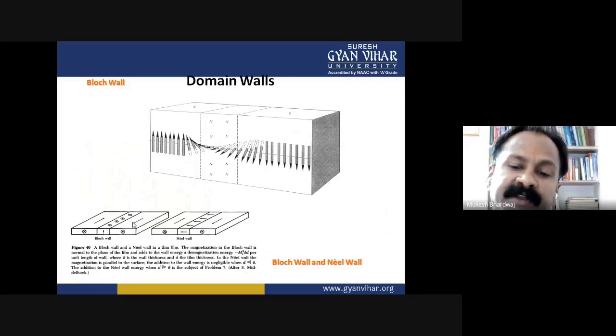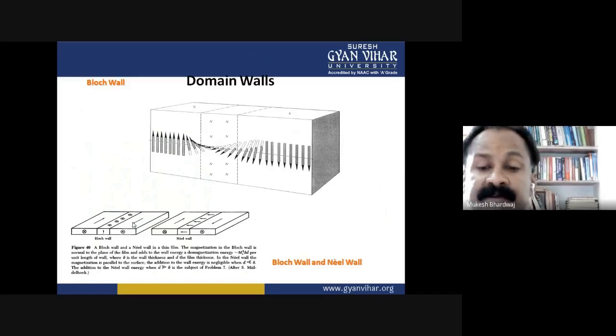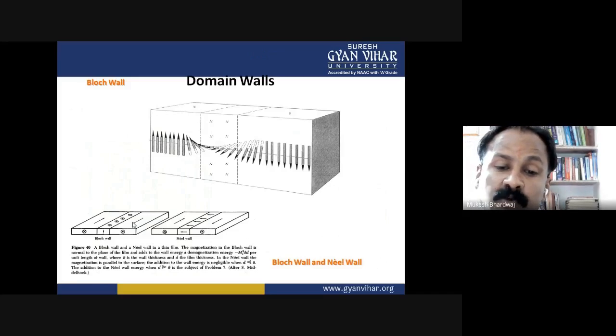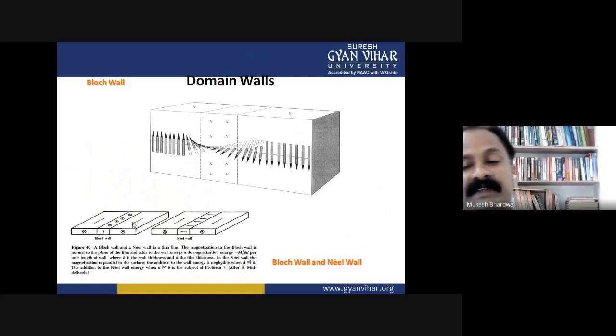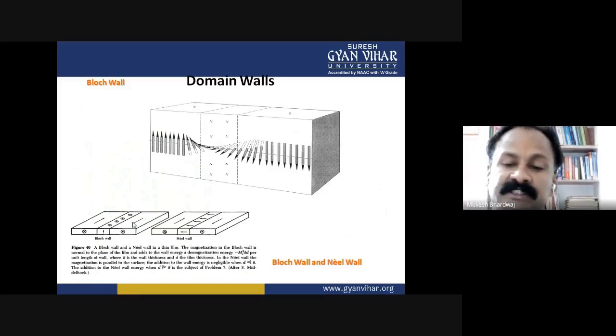In ferromagnetic materials, it is possible to exert some control over the coercive force Hc by taking advantage of the fact that domain wall motion occurs more easily than magnetization rotation. In permanent magnetic material, it is desirable to have large values of Hc through suppression of domain boundary motion. A high coercivity is assured. This is generally accomplished by using materials consisting of two metallurgical phases, which give a heterogeneous structure.